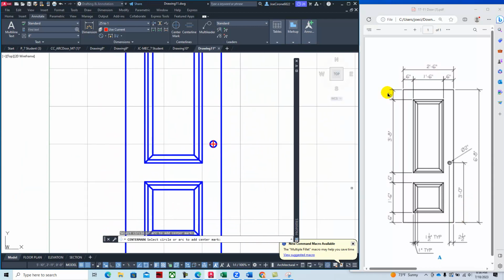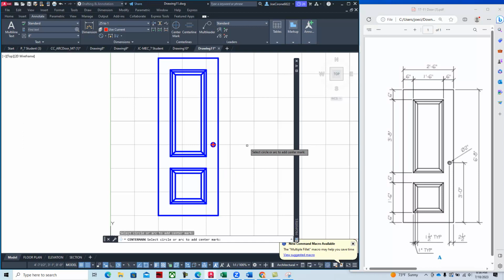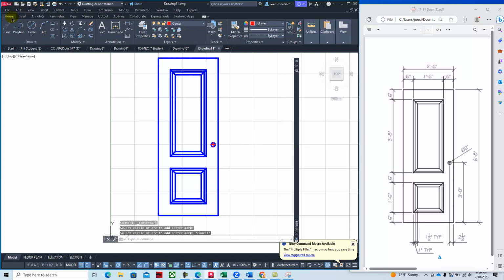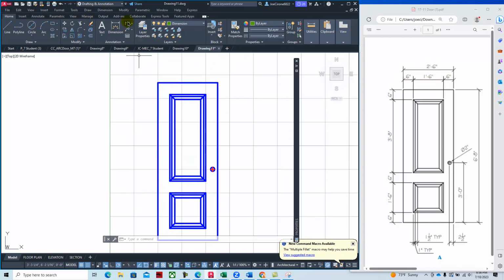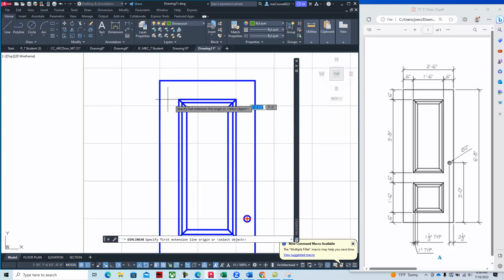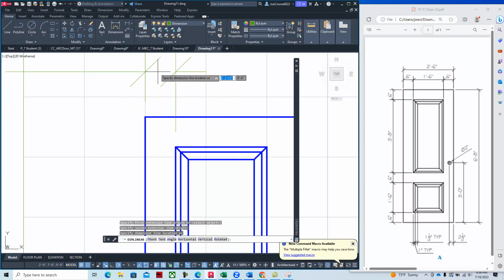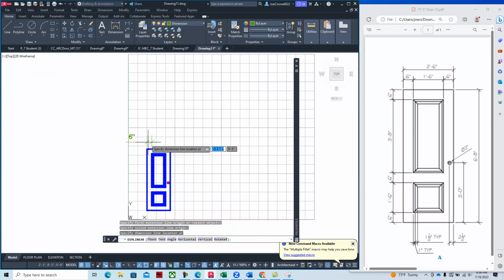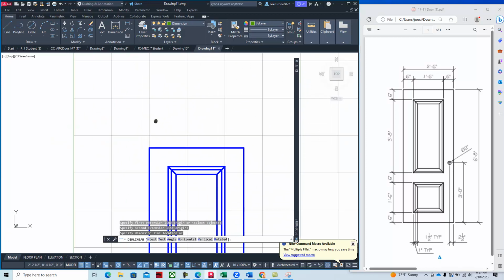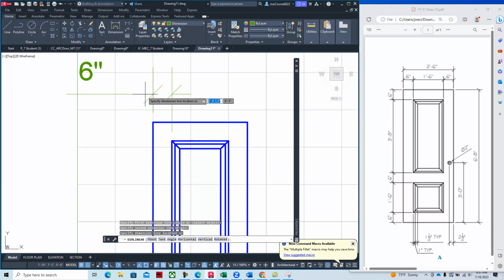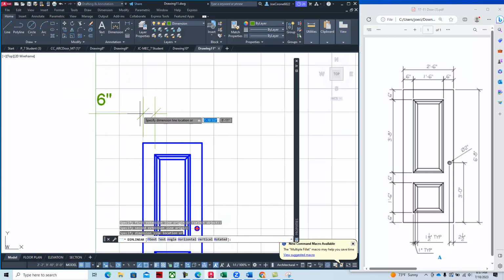And so now we're going to go through and add our dimensions. And so what we'll do is go to our dimension line layer. And we'll start off at the top and we'll put on these dimensions right here. And so we'll pan over there. Here's our horizontal line dimension. And I'll zoom in. And that's kind of how you want to, you don't want to have to go to the optometrist by trying to dimension things from way far away. That's the nice thing about working on CAD, is that you can make things as big as you need to make them. And so I'm going to drop this right about here. And then I'm going to add the other dimensions.